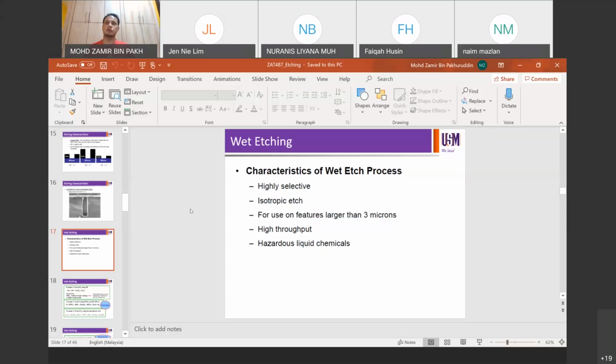In comparison to dry etch, as we're going to see later on, the process is going to be done in a vacuum chamber, and the vacuum chamber is not so big usually. So even though you still can do the dry etch in batches, the size is typically limited in comparison to wet etch, where you can just put your wafers in a cassette vertically and you can pack more silicon per process. So high throughput. It involves hazardous wet chemicals, hazardous liquid chemicals, just like HF,